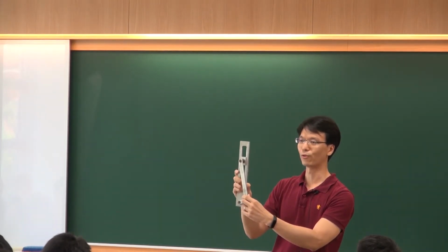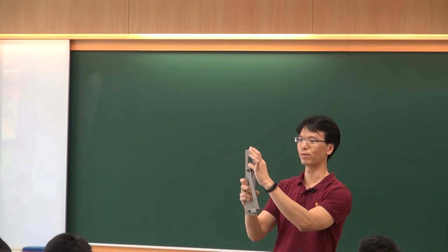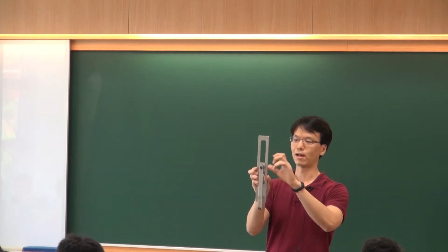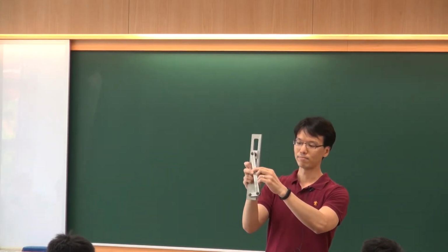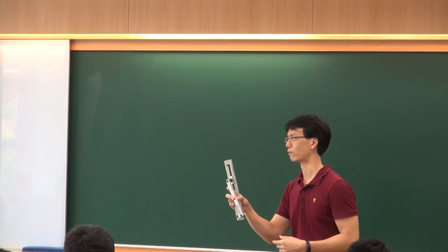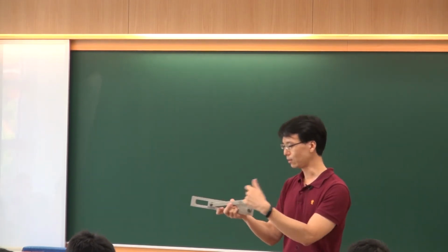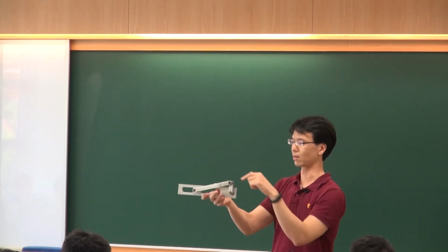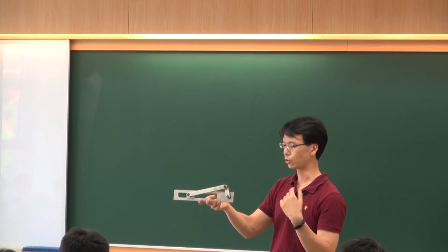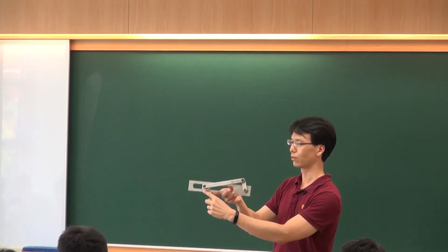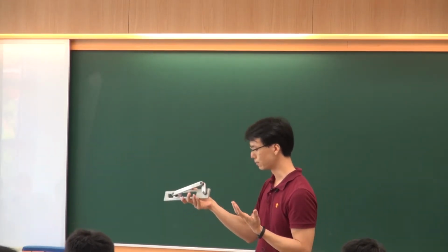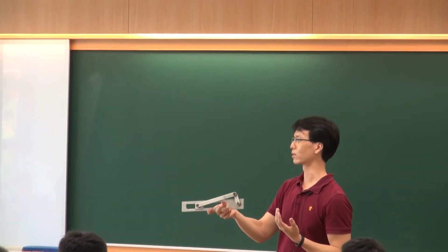So you know how an engine works? There is a chamber here, and it will cause some combustion. The combustion will push this slider down, and so make this crank do a full rotational motion. So that can drive your car or your vehicle. So in either of these two ways, we fix this big rectangular bar, and we use either this one or this one as input. So we transform either rotational motion into linear motion, or linear motion into rotational motion.